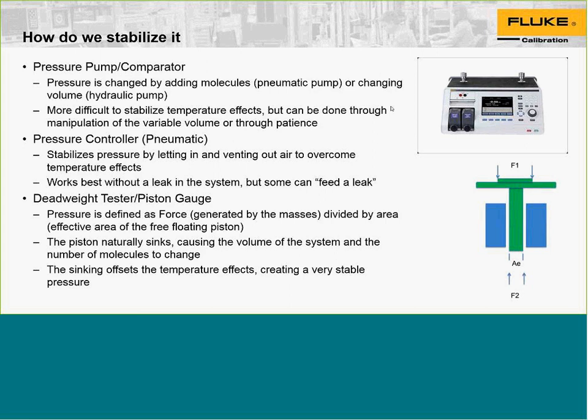But you need to be careful when doing this that you don't go too far past the point where you're causing hysteresis of the gauge. Hysteresis is the behavior of a gauge such that it displays a different pressure depending on whether you're increasing to get to that pressure or decreasing to get to that pressure. But a slight overshoot around the set point normally does not impact your ability to avoid the hysteresis.